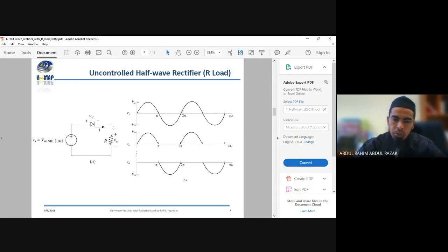So if you probe or simulate through a scope, you shall see that the output that appears on the scope or simulation is the peak value. So Vm here represents the peak value. If you want to present it in terms of RMS, we have to divide by root 2. Here Vs is the RMS value, and the instantaneous value equals V peak sine omega t. So this is V peak, this is RMS.